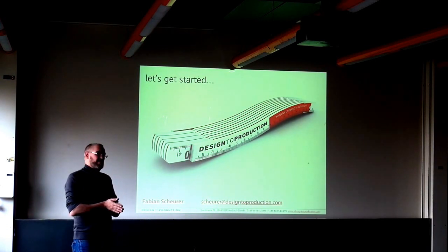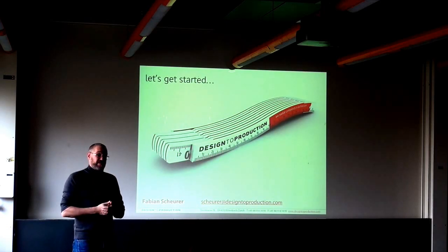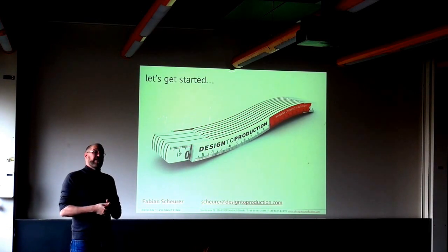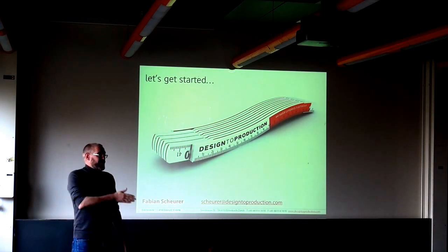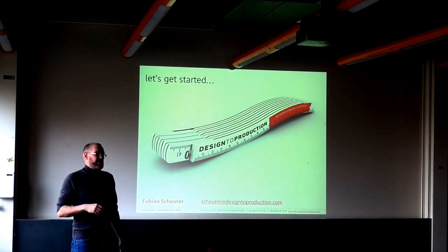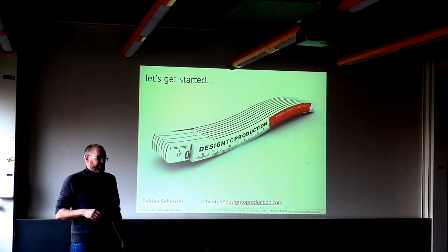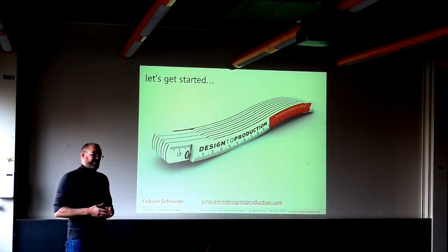As soon as you really need to be within 1/10 of a millimeter modeling tolerance, because you need that for fabrication in the end, the only way is to throw away the wrong 1 to 50 models and rebuild them from scratch basically. And the only way to do that is to start with a very simple input, which means a design surface and a few axes on the floor. And then from there on, everything is built up again in a proper way where, at least in a numerical fashion, points are at the right coordinates in space.